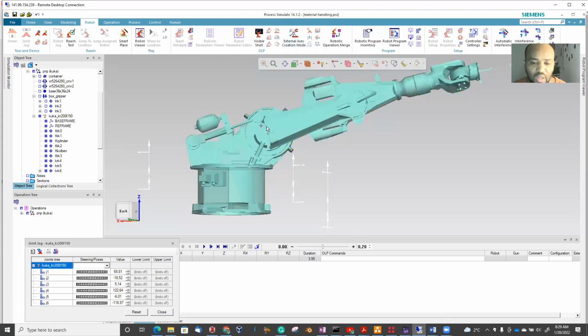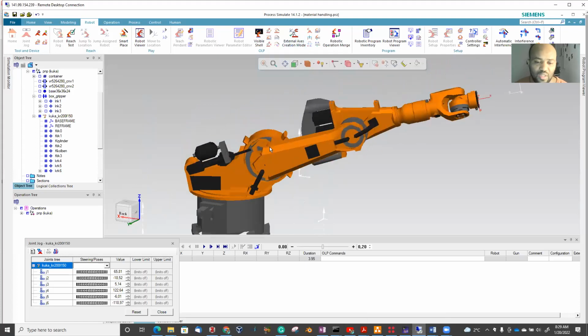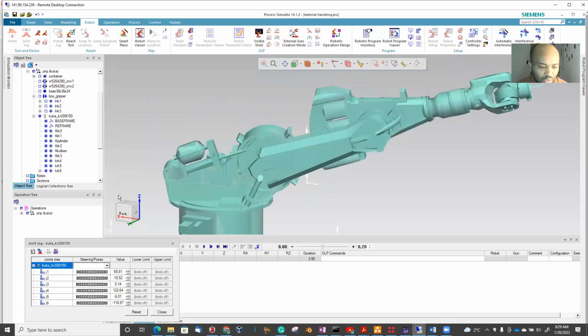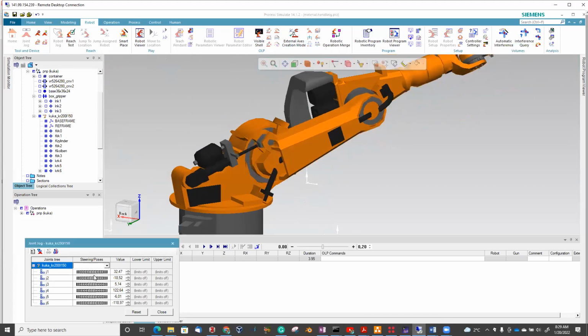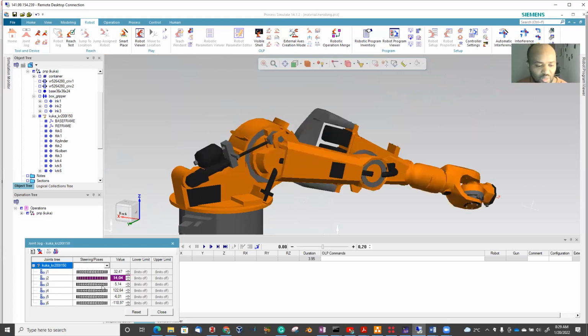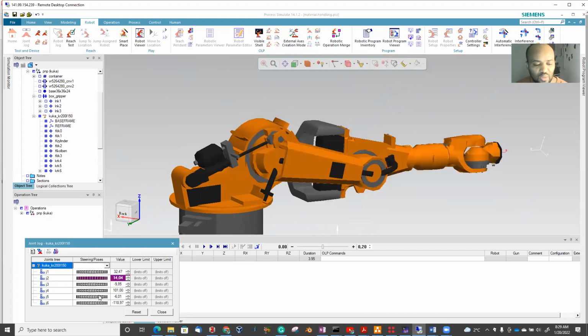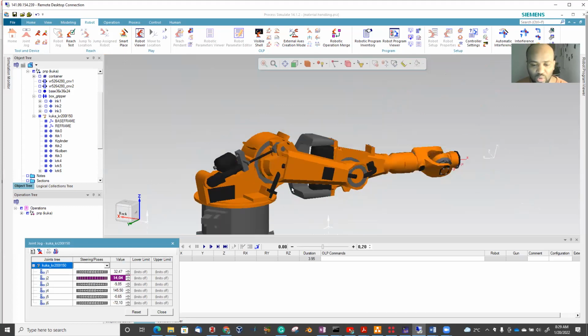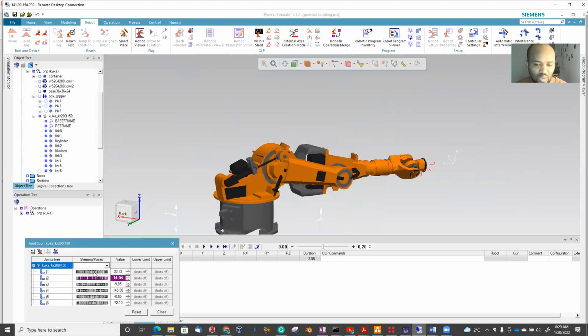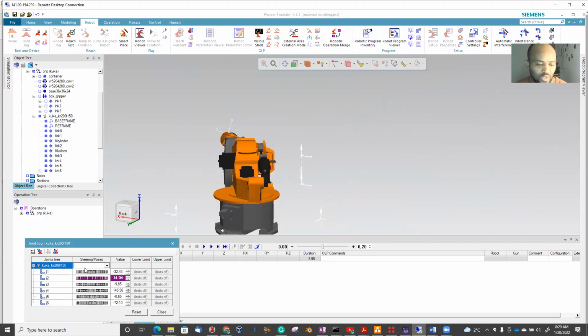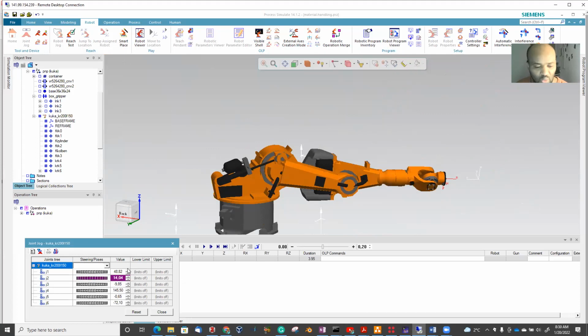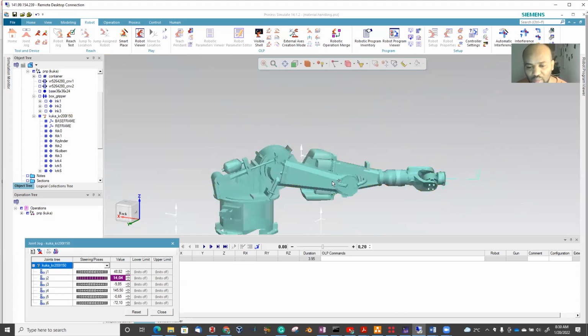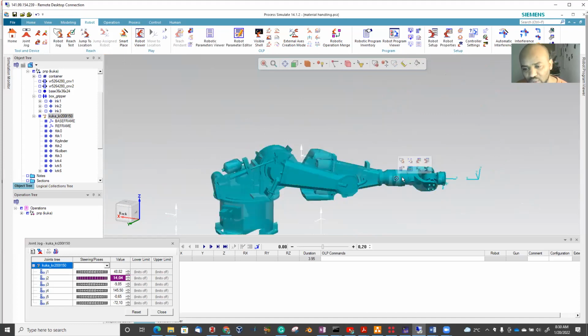Maybe we go to here. Now you will have coordinate systems for each joint. So here you have different values, different values, different values. Now when you have the overall homogeneous transformation matrix, then you manipulate the whole robot just with forward kinematics, which is a multiplication of 1 times 2 times 3 times 4 times 5 times 6. So it is 6 joints.